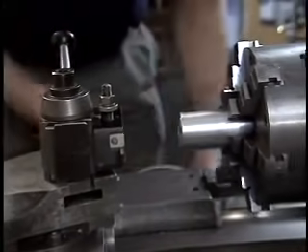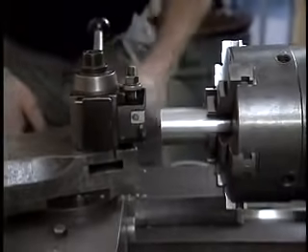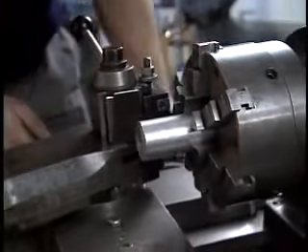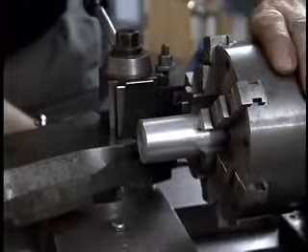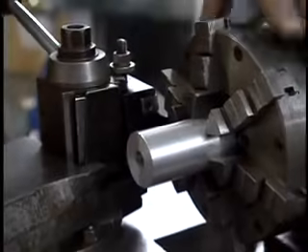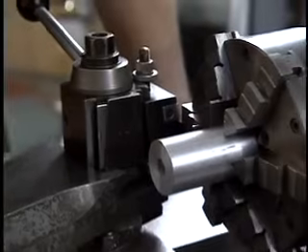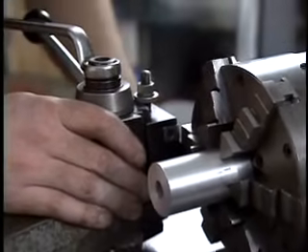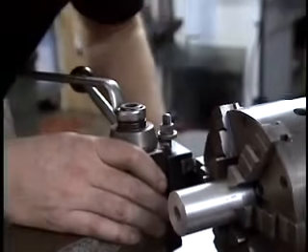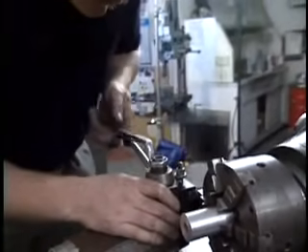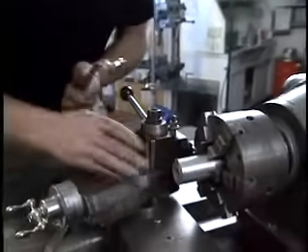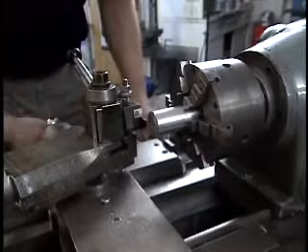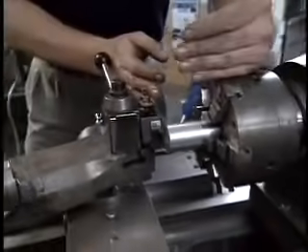Yet another alternative is to bring the tool all the way down here, either in contact with the face of the chuck, or, depending on the type of jaws you have, into contact with the top of one of the jaws. Again, you adjust the tool until you see it coming into full contact with the face of the jaw, and lock it into place. This adjusts the angle of the tool relative to the axis of rotation of the machine.